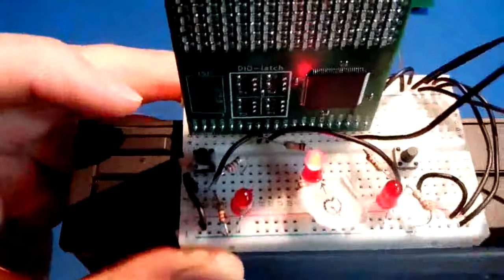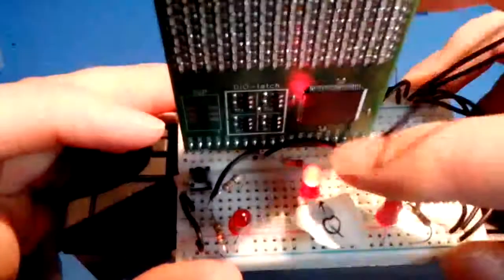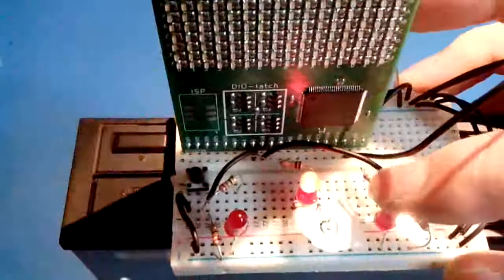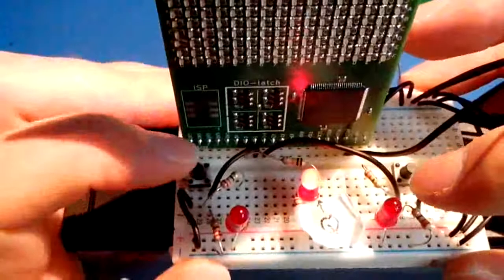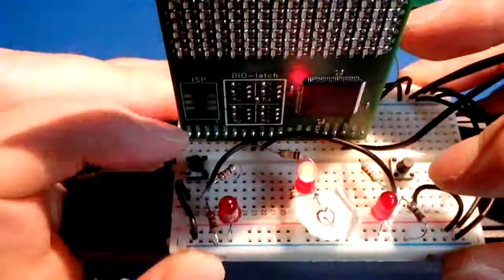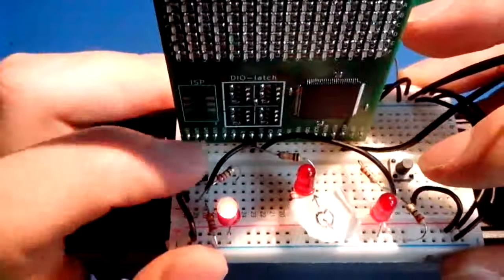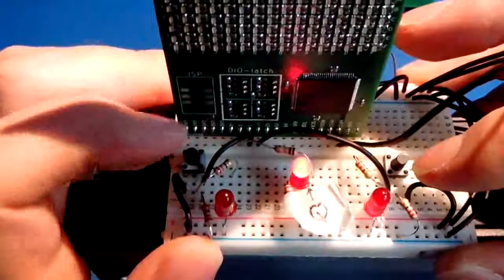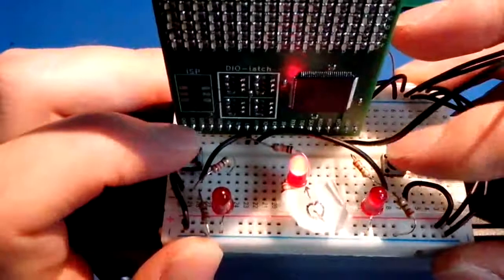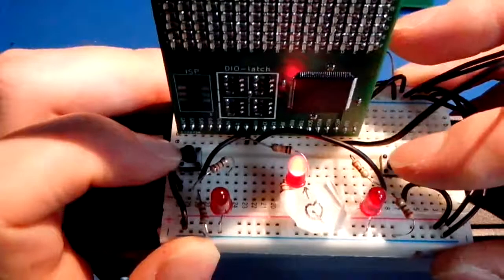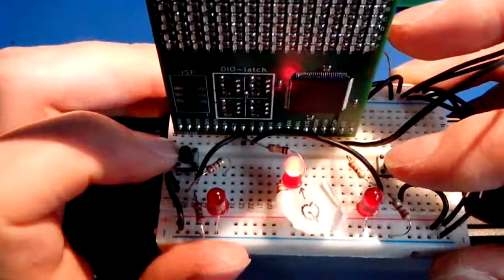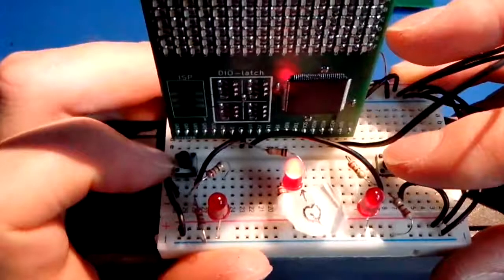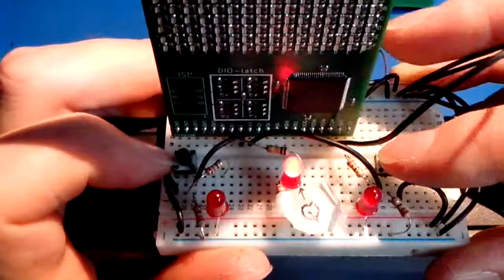Anyway, what you can see here is one LED, which is the output Q of the digital I/O latch. The LED on means output is high, LED off means output is low, or 0 volts. Leftmost button and leftmost LED indicate the enable input of the latch, so I can enable the latch by pressing the button, and once again the LED on means high voltage. The enable input is high active. The rightmost button controls the data input, so the DIO pin or the D pin of the latch. By pressing the button we apply high voltage at the high active D pin of the latch, a DIO pin of this module. It's just a different name.